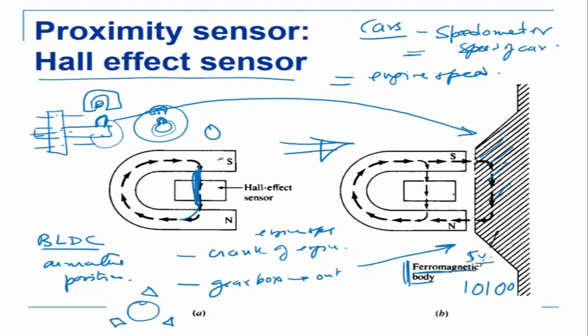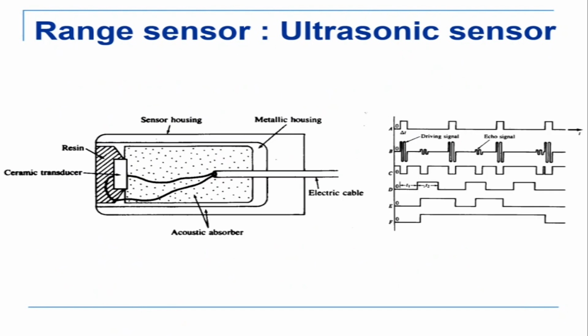So this is my armature which is rotating in the motor. When this is rotating, I need to sense the position for electronic commutation. This is sensed by placing 3 Hall effect sensors in this star formation. When the poles are rotating, they induce a magnetic field, and how fast it is rotating is checked by these Hall effect sensors. So it is also giving you the motor speed. When we come to BLDC motors, I'll explain how this is done.